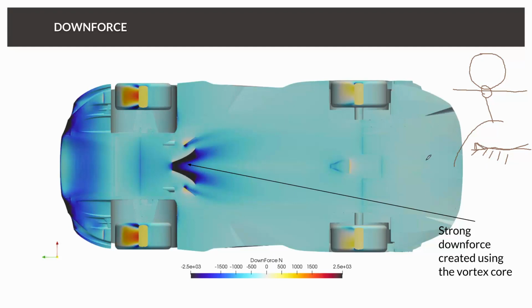The other problem is that in reality, the tire is not looking like this. The tire gets massively deformed. So what you should do is first try to find out in your application, for example a Formula 4 car, how the tire gets deformed and how it looks at high speed. Then you need to create what we call a tire contact patch, which connects the floor with your tire and makes sure you can mesh it.